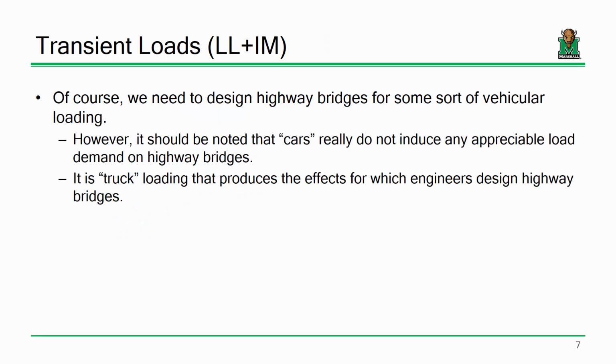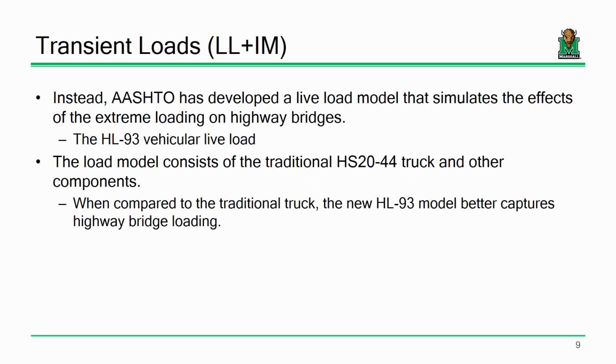Live loads, however, are a little more complicated. Okay? We spent a fair amount of time last time just defining what the heck the live loads even were. Because as we said last time, we're not designing bridges for Honda Civics. We have a particular type of vehicle that we're designing for, specifically exclusion vehicles, things like concrete mixers, tractor trailers, truck traffic. Heavy vehicular truck traffic is what we're designing for.